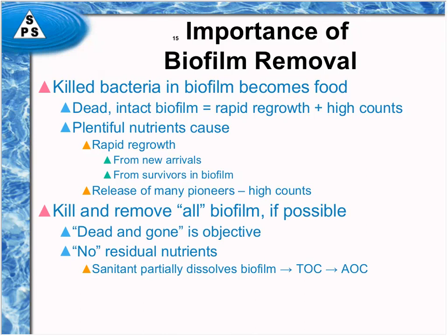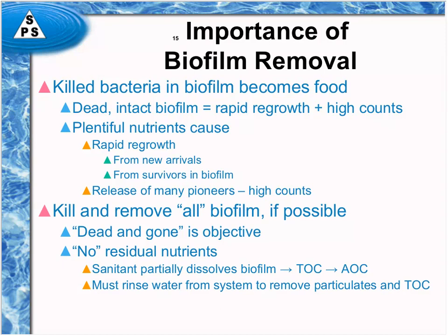And then as the sanitant continues to work on this TOC, it breaks it down into smaller and smaller pieces into what's called AOC, or assimilable organic carbon. In other words, bite-sized chunks of food that are much easier to digest than the larger complex organic molecules that may have been created by the initial dissolution of the biofilm.